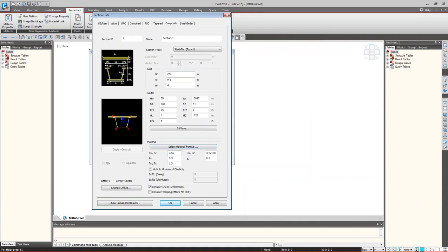If you're doing manual modeling, what you do for a composite section is lay the section first, and then at some stage you have the wet concrete load over the section for the slab, and that wet concrete load is still taken by the steel girder before composite action.